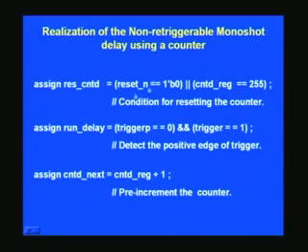So why not combine both in a single statement, and this is the OR statement that is doing it. This is a logical realization, and each of them will return a 1 if the condition is satisfied. For example, if counter 2 is 255, then it returns a 1, and this will influence this reset signal as such.